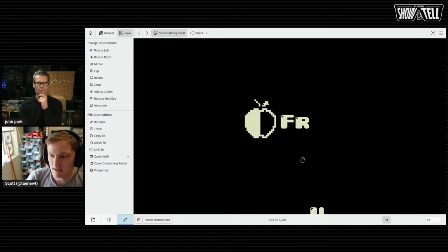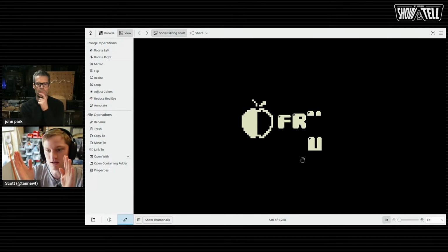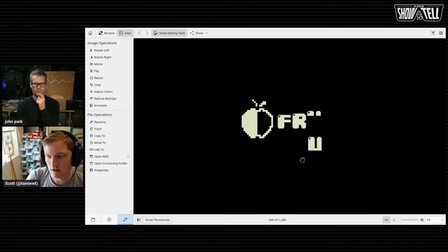It's interesting to see how displayio is rendering. For example, here's an interesting frame where it's updated part of it and not the other part of the frame. Right now there's no synchronization between when displayio updates the frame buffer and when it gets spit out to the actual display, so you get artifacts like this. The next frame looks okay, so the buffer wasn't full yet, and it got displayed.